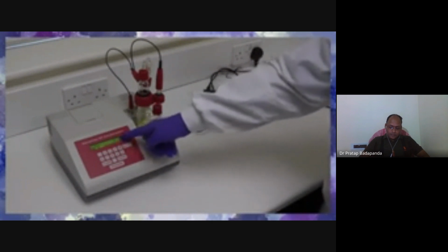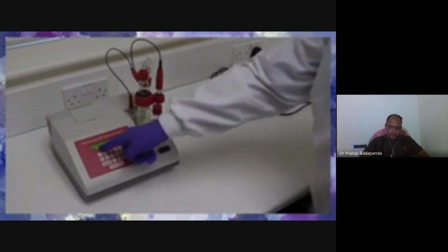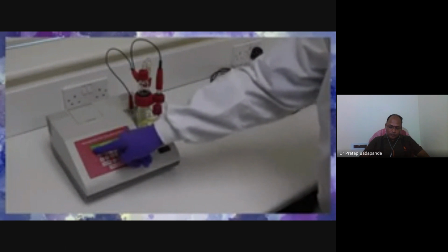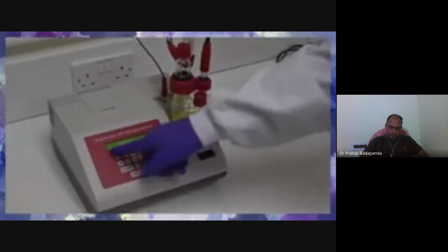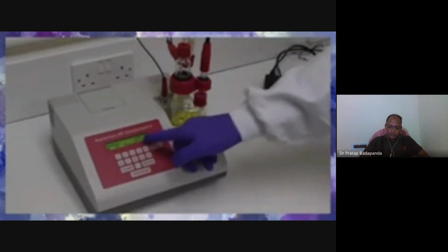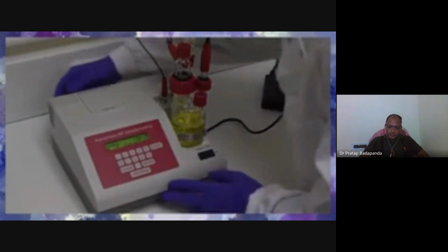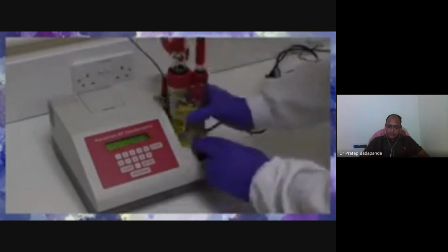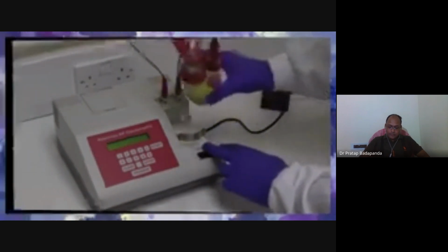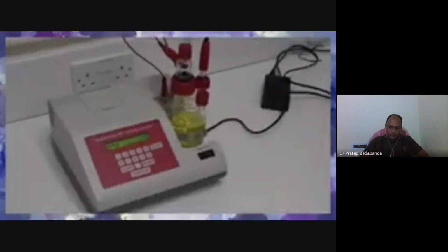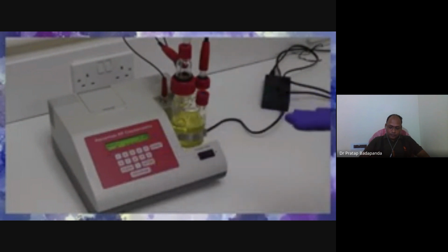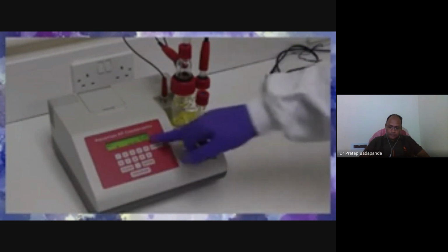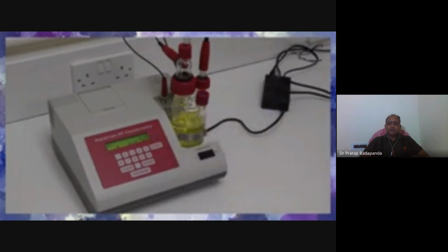The Aquamax KF moisture meter begins the precondition process, showing how many micrograms of water have been titrated, the speed of the titration, and the detector signal. After several minutes, and as the process advances and the speed reduces, settle any residual moisture more quickly by turning the unit off and gently swirling the vessel. After preconditioning is complete, the Aquamax KF moisture meter will monitor the background drift and then move into the ready mode once this is stable.